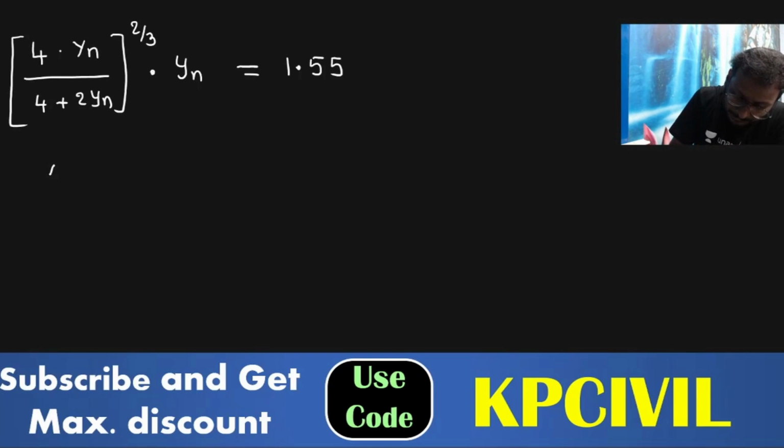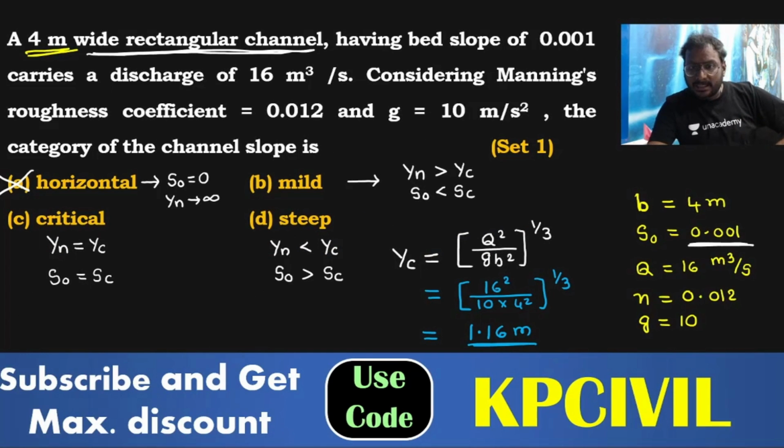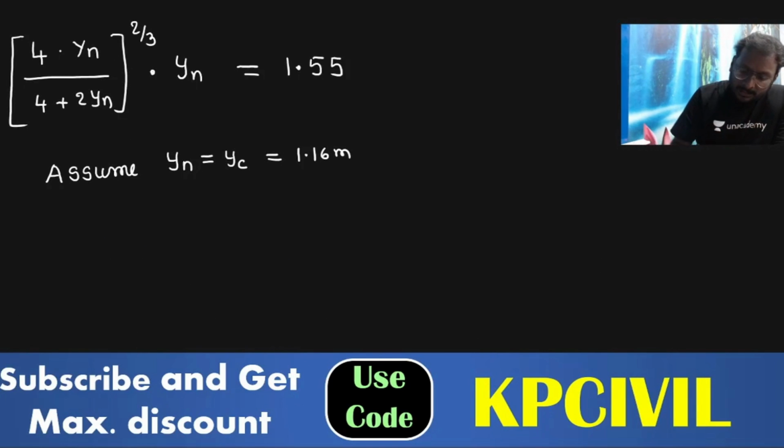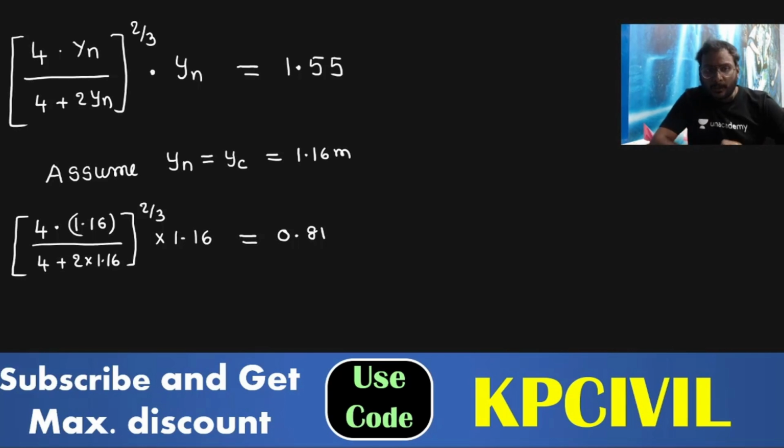So just assume yn is equal to yc. Take it as 1.16. You already derived yc, and that 1.16 meter is taken. Then substitute in it: 4 into 1.16 divided by 4 plus 2 into 1.16 whole power 2 by 3 into 1.16. If you solve this, you are getting 0.81.